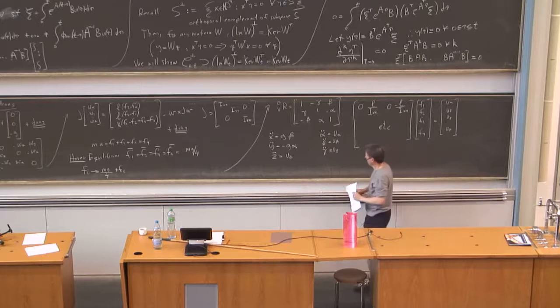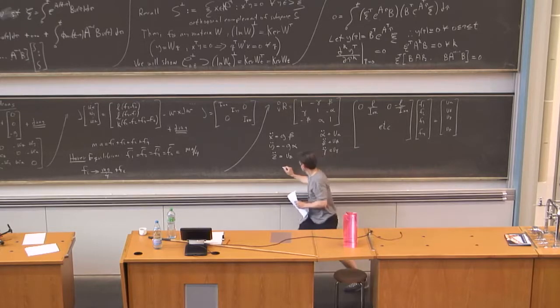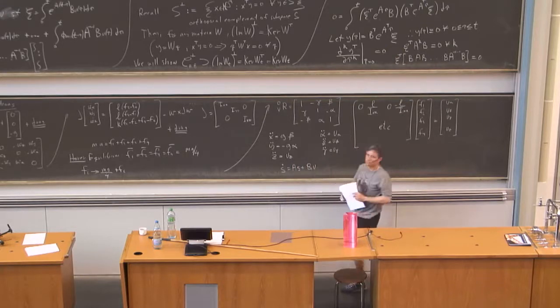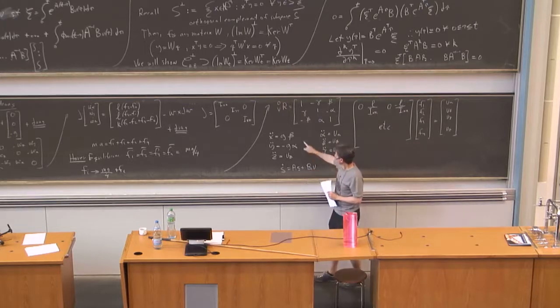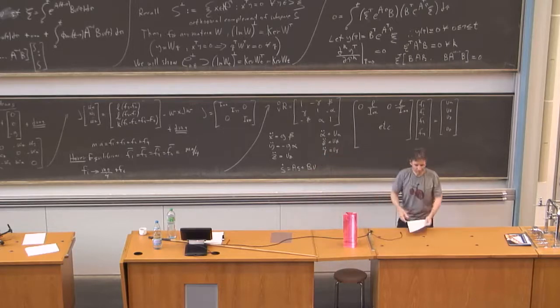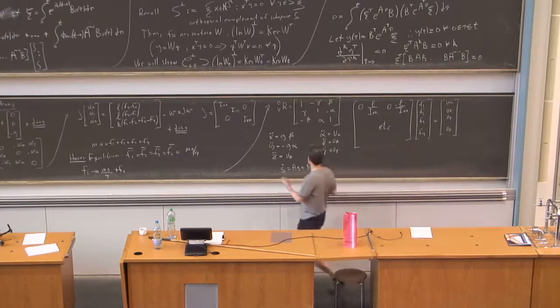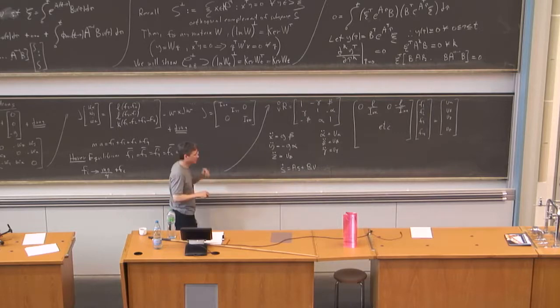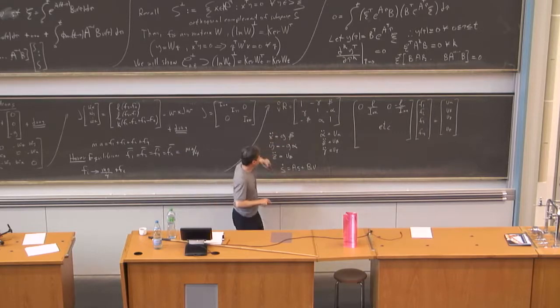And this can be written s dot is equal to A s plus B u. S is 12-dimensional, u is 4-dimensional, and if you look at this, you can find that it's easily controllable. In fact, it's even stronger than being controllable. You can see that all the axes decouple when written in this way.